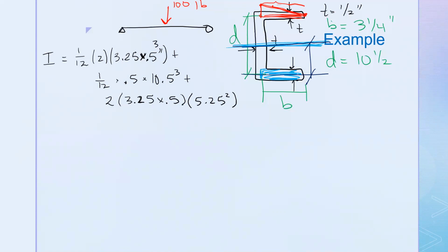Okay. So can we get a revised number? 137.88. Okay. Good. Are we all in agreement that this looks like a good I value? All right, V, how'd you get V? It's from the shear diagram. Perfect. What does your shear diagram look like? Go up, straight line, down 100, straight line. Good. And these are each 50? Yeah. Perfect. So V is 50. No matter where we're looking in this beam, it'll just be opposite directions.